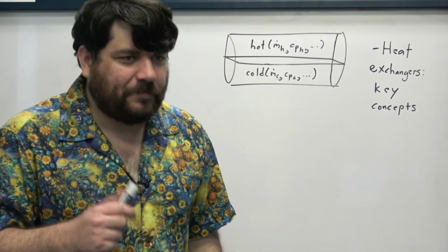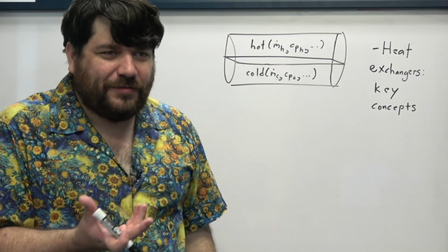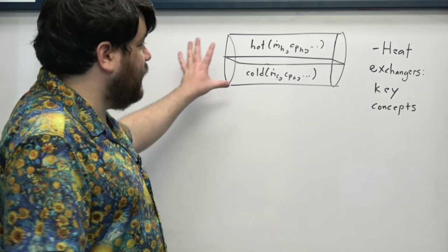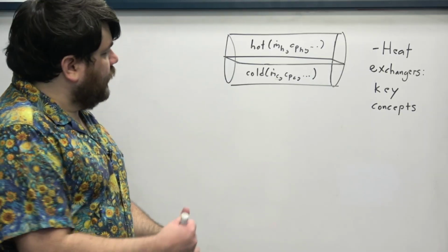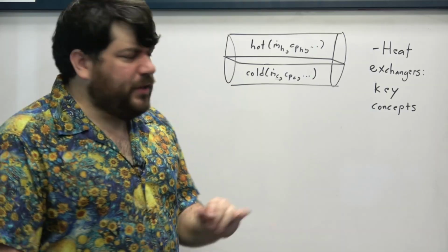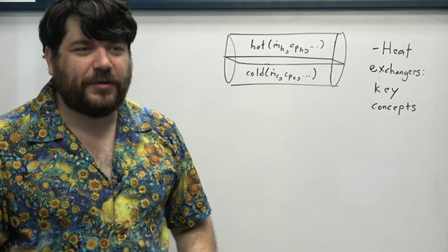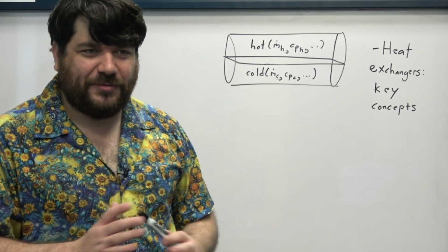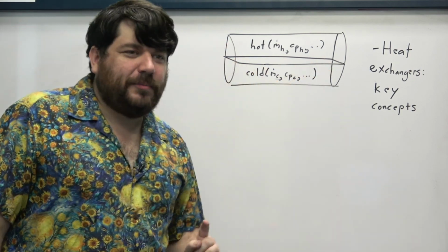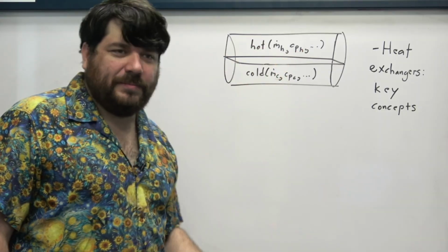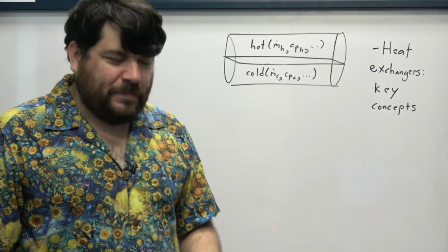And so when we make those sorts of assumptions, when we try to simplify the way that we analyze the system as much as possible, it turns out that understanding these systems is relatively straightforward, at least conceptually. So what is going on here? Well, we know that there's temperature differences that are going to occur from the inlet to the outlet for both liquids, whatever those temperature differences may be, right? Just as we had seen with internal flow, the liquid changes temperature, and so therefore the temperature of the liquid throughout the duct in either case is not uniform, okay?